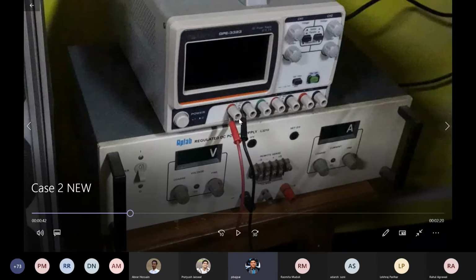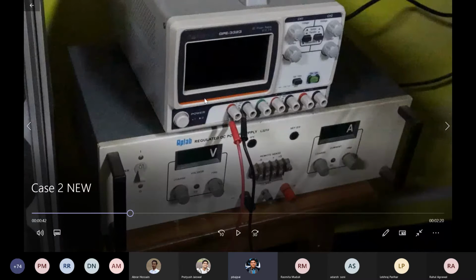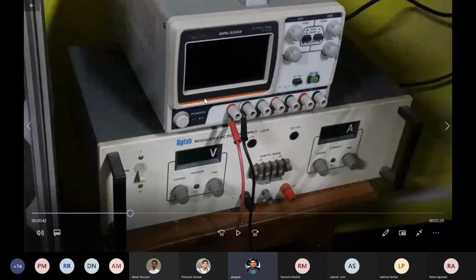So this panel is connected to this regulated DC power supply, and no lamp is on. So it is a dark condition. No insolation is available. The panel is covered with a dark cloth, so no tube light or any kind of light is coming on the solar panel, right? And then we are applying a voltage to the panel. So basically we are trying to get the diode characteristic. The module is basically inherently a diode, so we are getting a diode characteristic from this test.